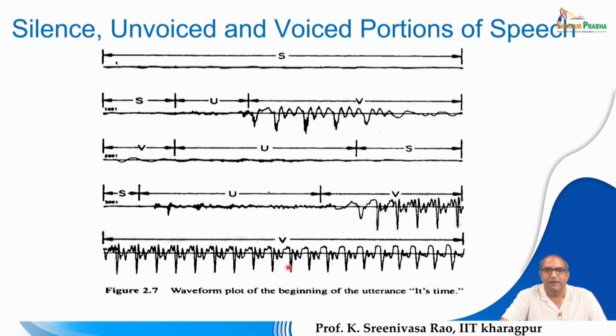But here, again, the shape of the signal is varying: half of the signal has a periodicity with some kind of pattern, whereas in the remaining half we have some slight change in the shape of the signal. And in the speech signal, this periodic part of the signal in the time domain is known as voiced speech signal, because you are observing this periodic pattern in the speech signal because of the periodic excitation, or the voiced excitation.